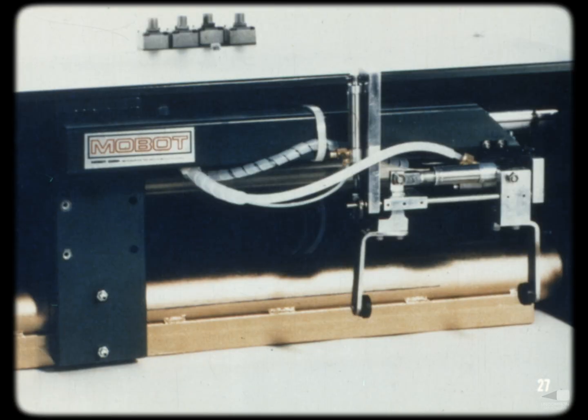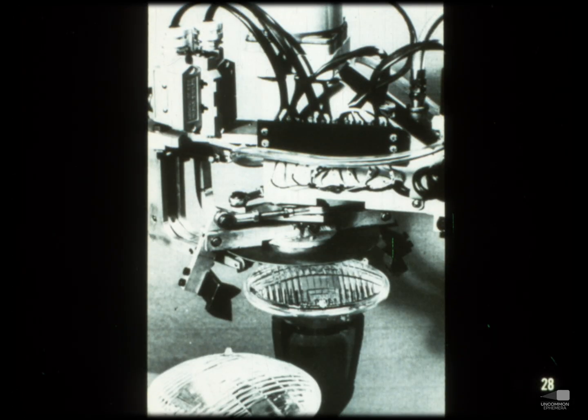Pneumatic systems are commonly found in the fast-operating, low-power, limited sequence or low-tech robots. Compared to all other drive systems, pneumatic systems are generally the most reliable, thereby decreasing possible maintenance costs. However, the speed and position of a pneumatic system can be difficult to control. Pneumatic drives are therefore used primarily in the less precise pick-and-place, limited sequence robots.